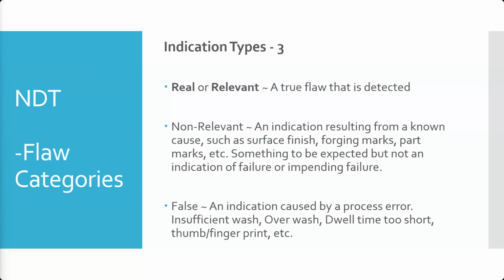Once they found out that there was this cracking condition, we would perform that inspection and note how big the crack was. And then we would have to go back on a regular basis. Again, it was based on flight hours, because engine hours. I don't remember the exact number. I'd have to get the whole procedure in front of me, and I don't have it. But after so many hours, we would check it again.